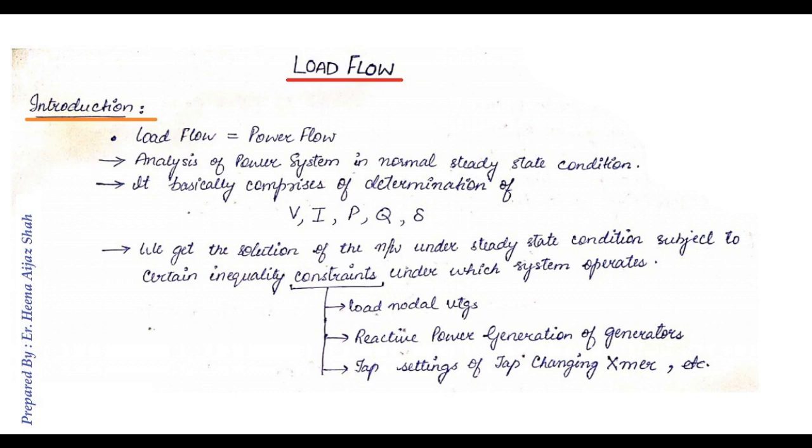Now, we are all familiar that if we have just one equation, we can simply solve that equation. But when we have a number of equations, we deal with those systems using matrices. Similarly, in load flow analysis, we have a system which comprises many equations in terms of power, voltage and phase angle. So to deal with such systems, we use the matrix method to analyze the system using load flow analysis.